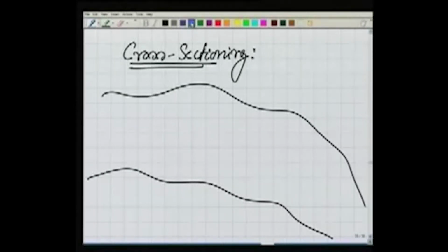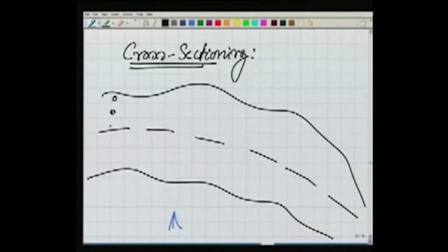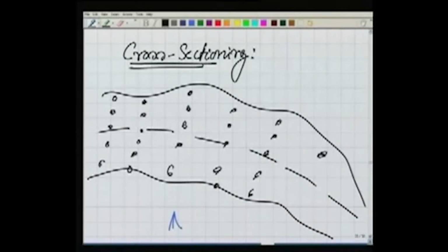How do we do it? If I keep my level here, I would like to have an arrangement of points here. Let us say the points are arranged in such a way that these are the points for which I want to determine the RL. For all these points, our desire is to determine their RLs.